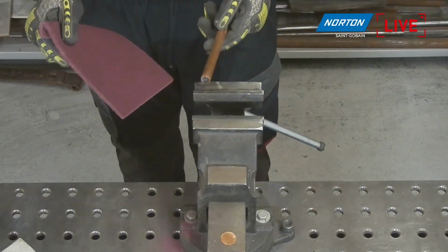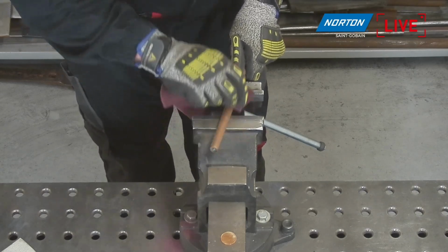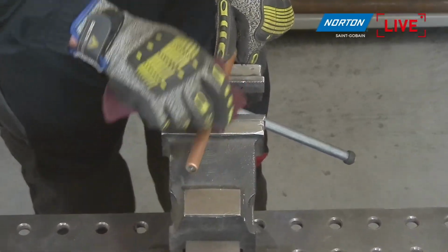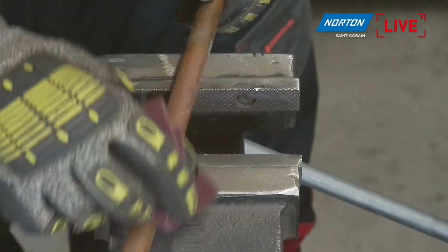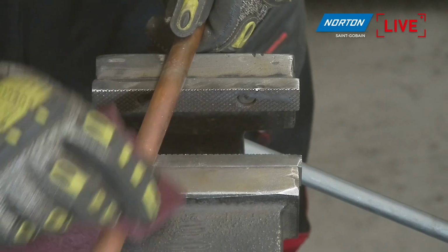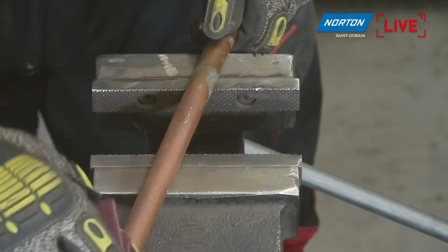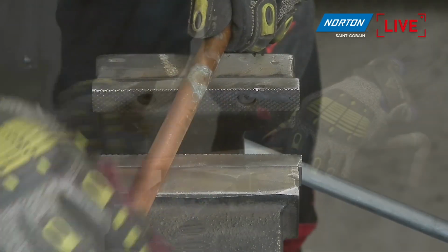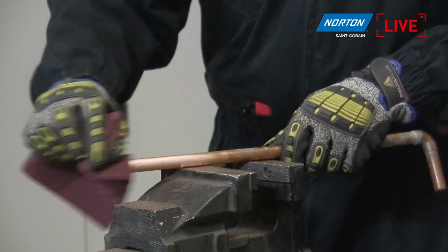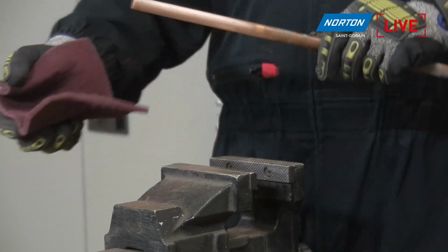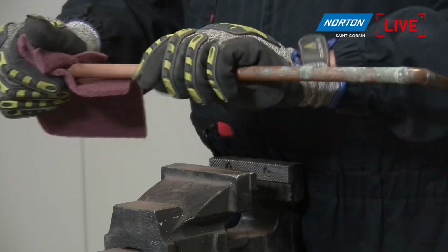With a very fine pad, very, very quickly, we can take that finish away to a very nice, bright finish again, just like when you bought the copper from the DIY store, from the plumbing centre. So you can see really, really quickly we can clean that copper up. And any of you plumbers out there that do use this copper rather than plastic and push fit these days, you can see what an advantage this would be over the traditional wire wool where you'd use to clean up the end of this copper pipe before you actually do a soldered joint.